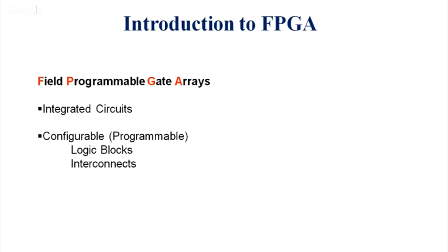From a research point of view, implementing our research or hardware on FPGA is much better than on a microprocessor or microcontroller. The most important beauty of this FPGA is that it works on a parallel, concurrent basis, meaning we flow data from input to output. In the case of a microprocessor or microcontroller, we first write instructions or our program and store it in memory, then fetch these instructions one by one and execute. So it works on a sequential basis.